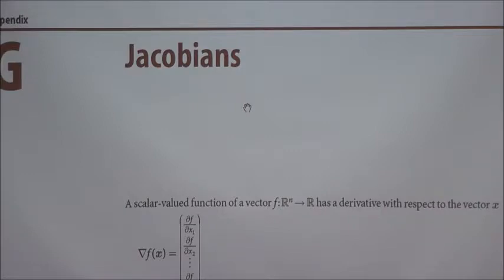Sines and cosines are all over the place. Those are some of the nonlinearities we're talking about. So in order to use Kalman filtering for robot localization, as you will see in chapter 6 very soon, the standard Kalman filter is not appropriate because the robot is not linear time invariant. So what do you do? You linearize it, like a Taylor series expansion. You find a nominal value, nominal velocity, nominal position of the robot, and you linearize around that nominal location.